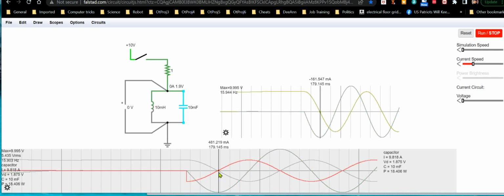Now at that point, remember what I was saying about the inductor generating whatever voltage it needed to try to maintain its current. It's trying to stop itself from losing current, but in the process that's leading to its own demise because it doesn't have unlimited energy to do it with. Well, just before the inductor current goes to zero, it's still generating a voltage across the capacitor that's infinitesimally small, but still greater than the voltage across the capacitor. But once it hits zero, that stops.